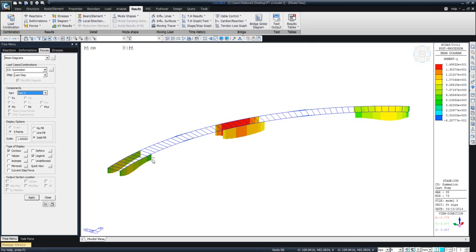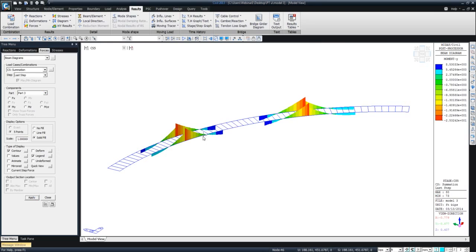Part 2 for other sections is the girder or the deck, and part 3 is only available in a certain span. So you can see how the bending moment is shared by different parts of the composite section. But if you look at the overall picture as total composite section forces, you can use these forces to design your sections.